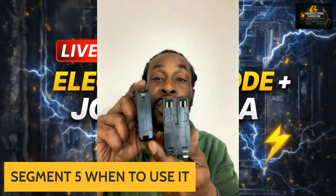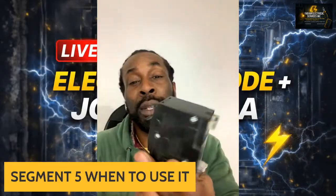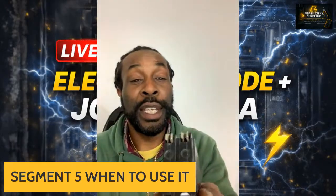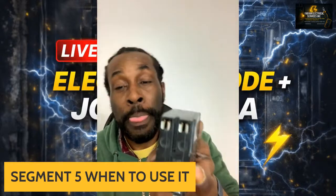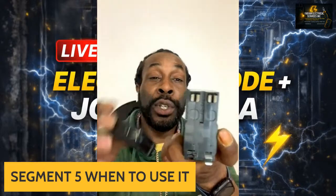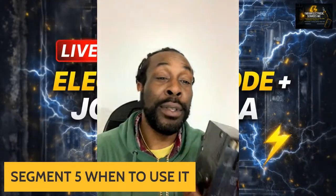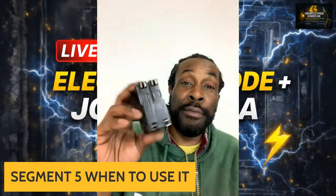As you can see, this is a Schneider brand. This is a Square D brand. You can see the teeth here; the teeth are a lot different from this. So this can only go into a panel that is Square D, a specific panel designed for that.